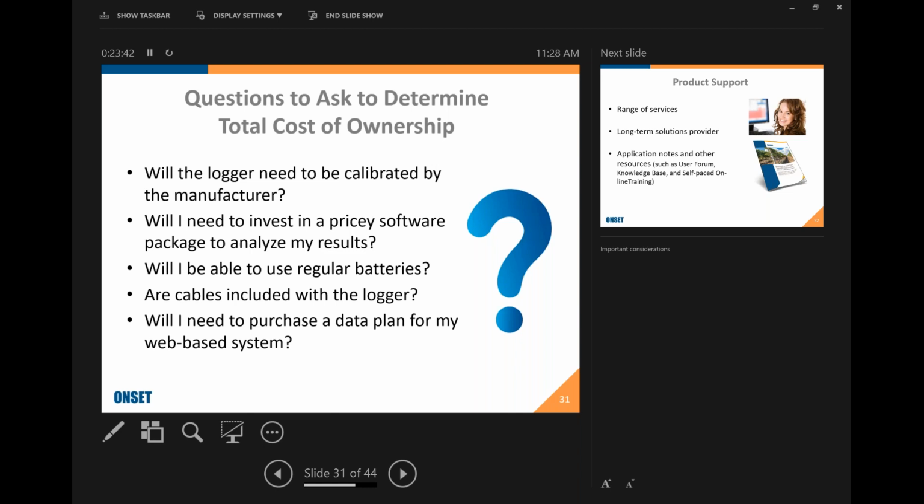But these devices all come out on the temperature side, because that's usually where people want to calibrate, with a digital thermistor on the temperature side and an RH sensor that if it does drift, it won't drift any more than, say, plus or minus 1% per year. The beauty of it is that the sensor of the internal data loggers is built in to it, and it can be replaced as well for a fee. So calibration, these things hold their calibration really well.